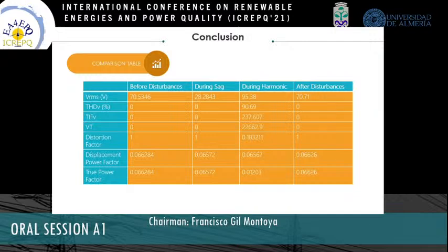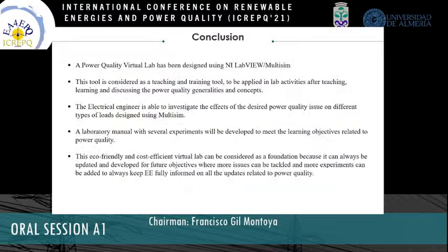And while the displacement power factor remains the same even with the presence of harmonics, the true power factor gets smaller as harmonics are added and becomes less than the displacement factor. Both TPF and DPF are equal in non-harmonic situations. To sum it,